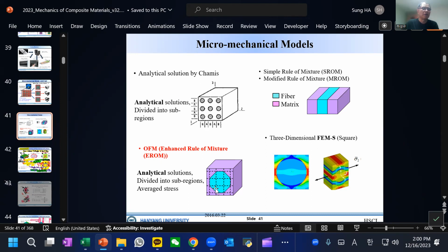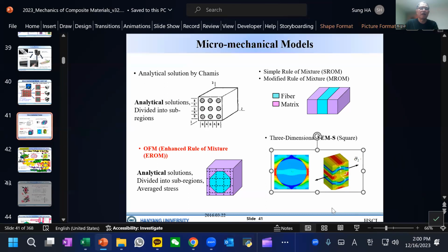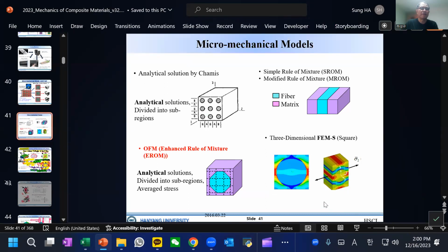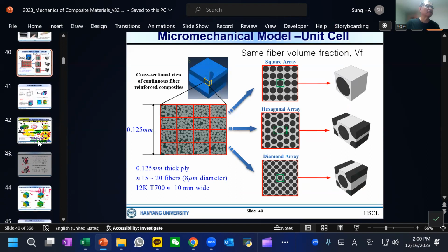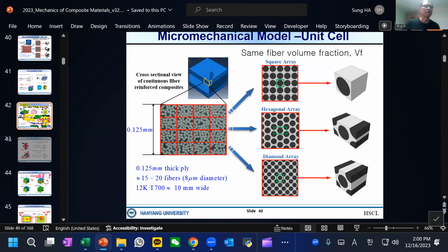With this, we can derive all the analytical solutions on the transverse load and the shear load. And you can use FEM, like Abaqus and ANSYS, to arrange the fiber and resin system. So anyhow, once you model them, you can come up with this, or you can just directly model the random fibers, which is also one choice.